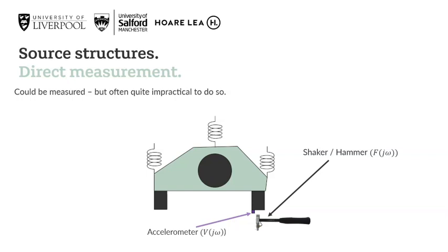This would necessitate the purchasing of force hammers or shakers, multi-channel systems, and a suitable test rig to perform the test. And we'd also have to ensure that the mass spring resonance did not affect or colour our measurements when we look at the overall frequency response. From a practitioner's point of view, such an environment or perfect laboratory conditions are rarely afforded to us.